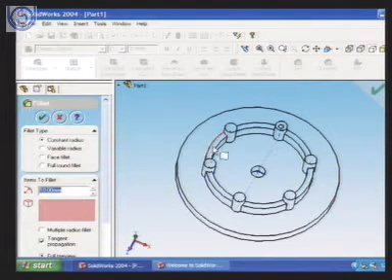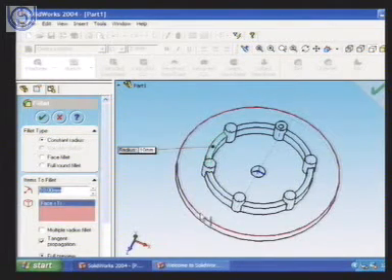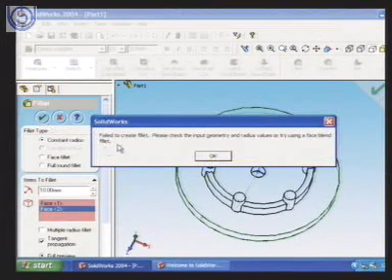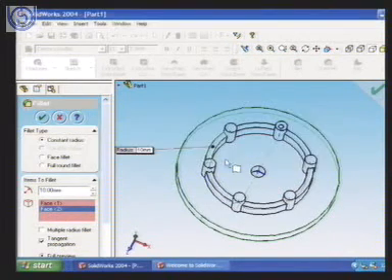and I select this and I select this, will it do it? Let us see. It doesn't. Why has it not done it? Because can we create a fillet of 10 mm radius here when the thickness is 5 mm?